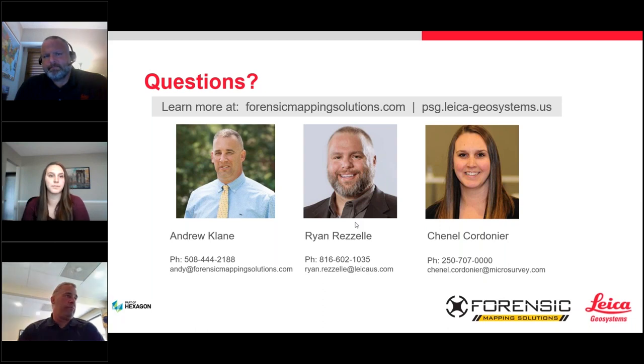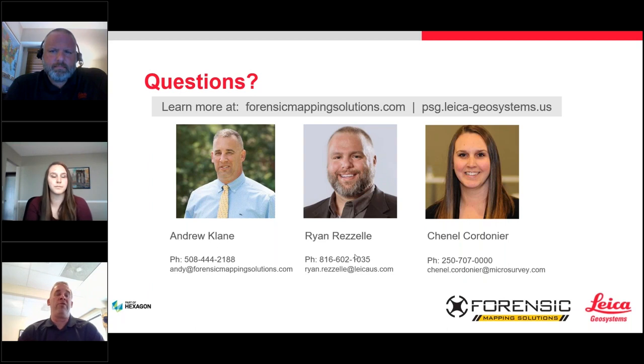Okay, thank you, Andy. And you did mention a little bit about unlocking the DJI drone. One of the questions we had here is, do you need to contact DJI to unlock NFZ? Yes, it has to be done through DJI. We're going to post the information so you can do that. Basically, you're going to have to fill out paperwork, and they're going to want the serial number of every controller that you have for each aircraft. And they will literally go and unlock that geofencing for a year. So it has to be done up front, and they're going to require official letterhead. They're going to require the serial numbers. So we'll give you directions to get to the location to be able to get instructions and the forms that you need to do that.